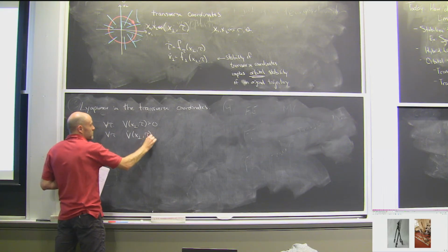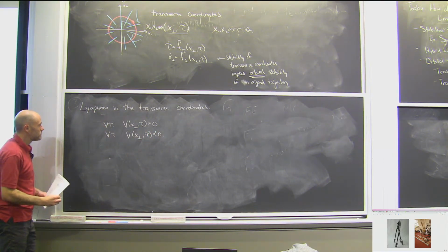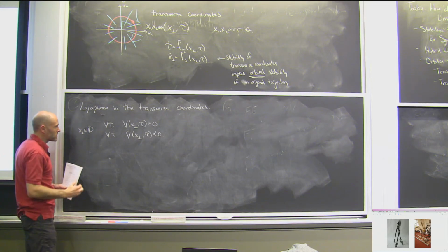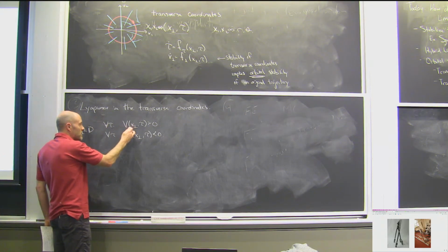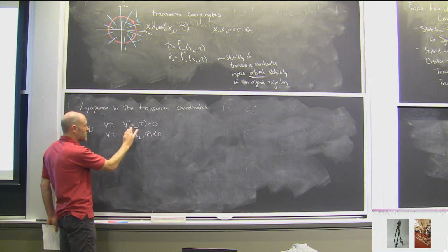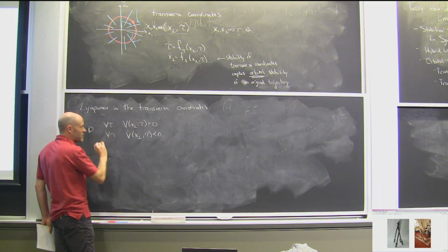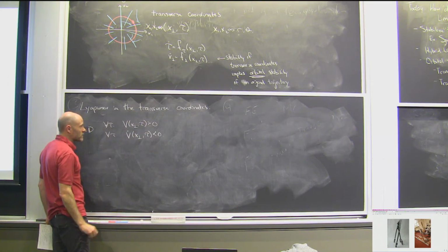But I could take x bar in some domain if I want to talk about local stability. If I can find a v, you could think of this almost exactly like what we wrote about time-varying Lyapunov functions before, right? So it's now a tau-varying Lyapunov function where it's a positive function, its derivative is down.